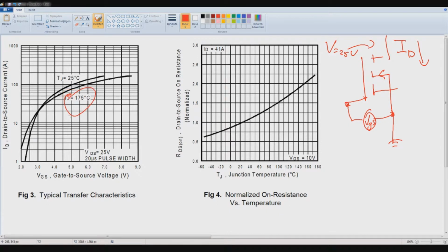This is the maximum rated junction temperature, and this is about room temperature. So if we see here, we can see 3, 4, gate voltage up to 9, and over here we can see all the way above about 180 amps, but as you remember, this was rated for 45 amps, and perhaps it comes from the logic level.